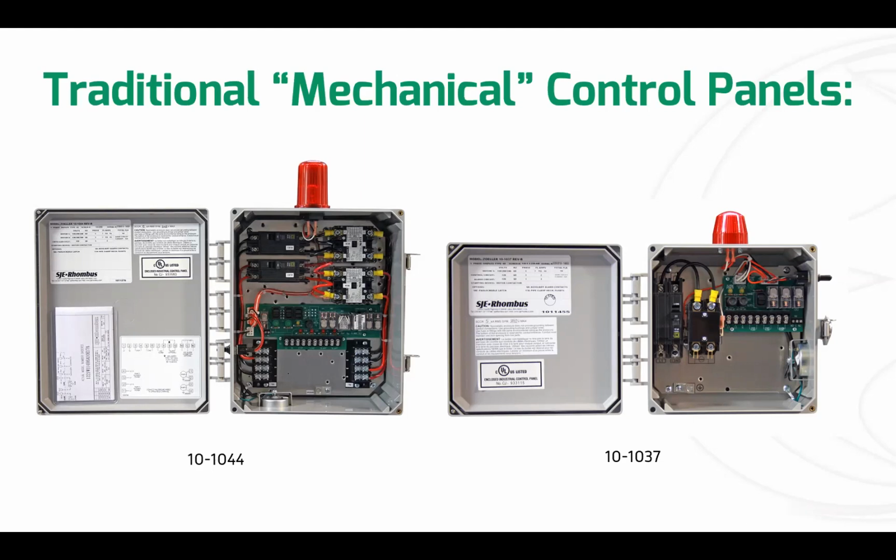In the upper left corner of the left-hand panel, the duplex panel, you've got 2 circuit breakers. On the upper right, you've got 2 contactors. You've got a board with some HOAs, which stands for hand-off-auto. And you have the terminal strips where you're landing everything. So real easy, real simple, relatively inexpensive.